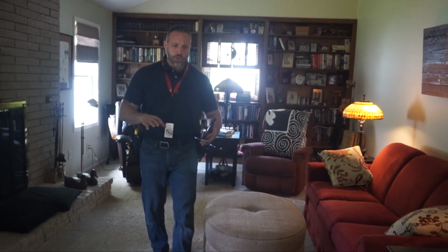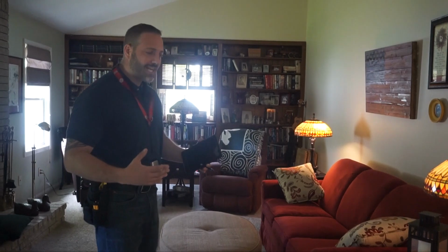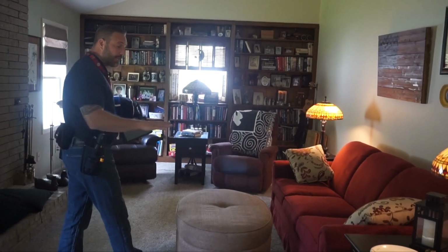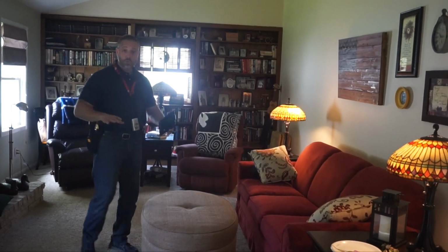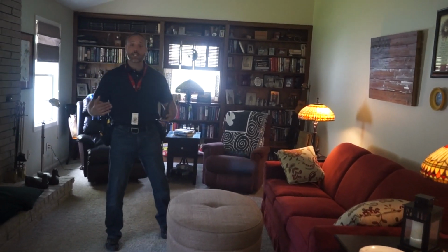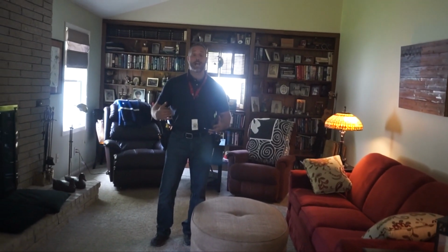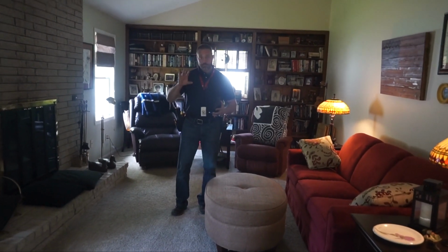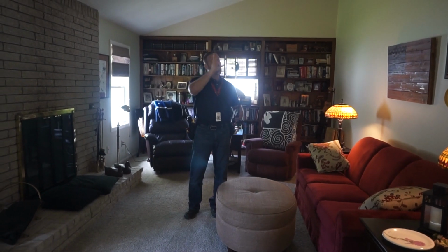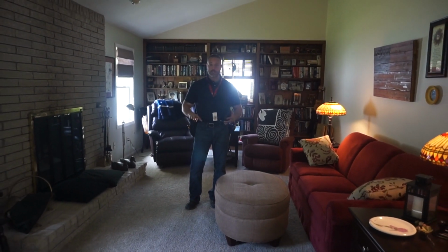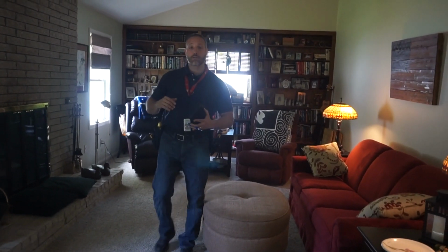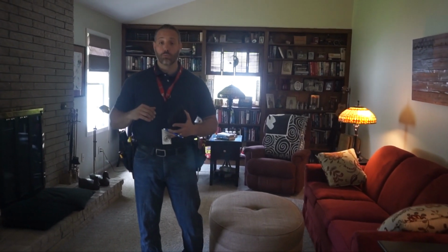All right? So when we're walking along the floor, what we're trying to understand is the floor level. Is there any unevenness? Is the floor squeaking? Because that'll give us an indication of where we want to look inside the basement in that location. Now, as we looked at the ceiling, and we looked at the walls, and we looked at the floor, we have to test a representative amount of windows in each of the rooms.